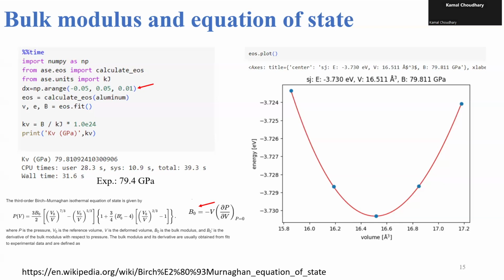So hopefully we learned how to calculate the optimum structure, elastic constant, and bulk modulus of aluminum. And the fun part is if you want to simulate another material, you can just enter any other material in terms of its atomic coordinates and calculate its properties. This is very useful, especially for R&D applications.